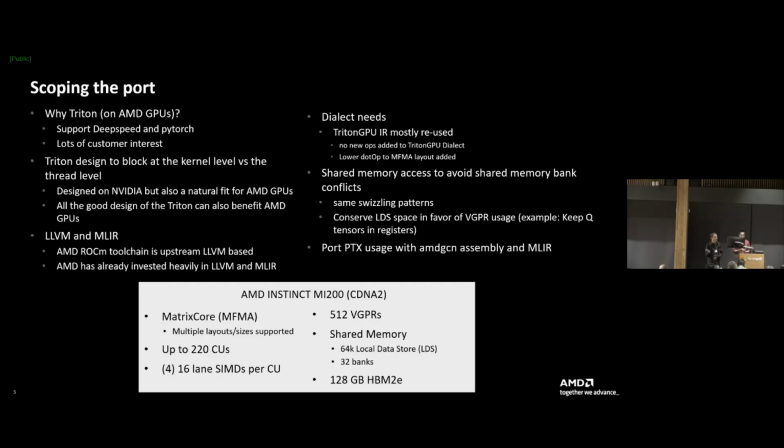So at this point, it came down to more of a tuning thing, right? We want to prioritize our general purpose registers more, and try to be more conservative on the usage of the shared memory, and that is evident in some of the pipelining passes that we're talking a little bit about today already. We'll talk about a little bit more of that in a second.